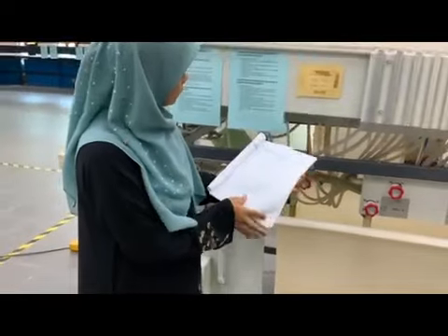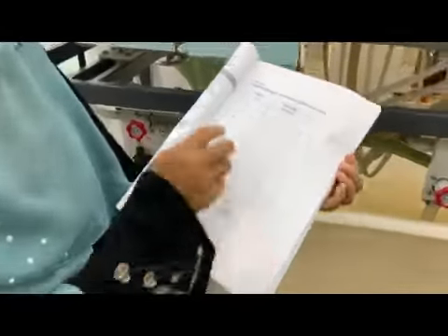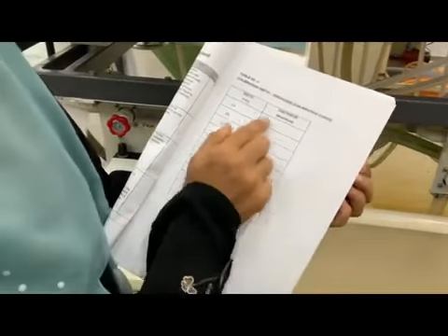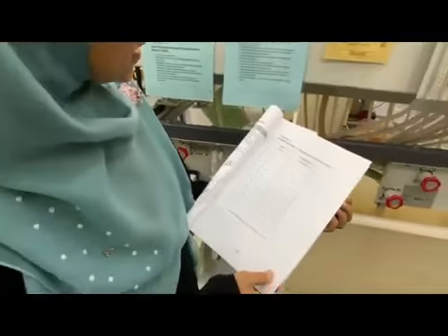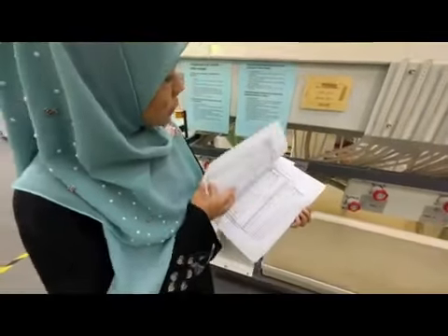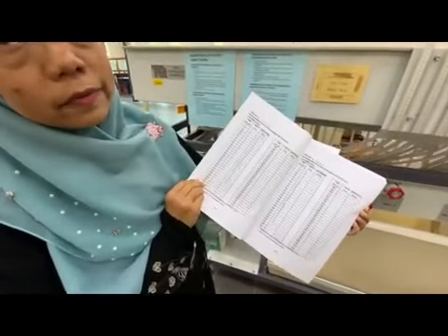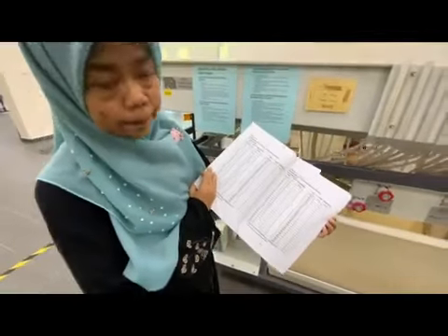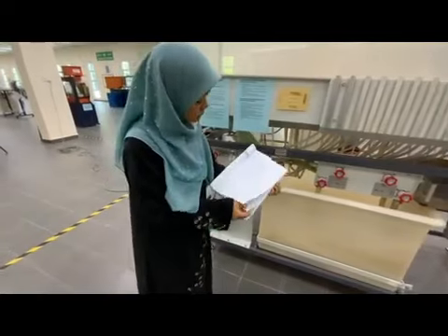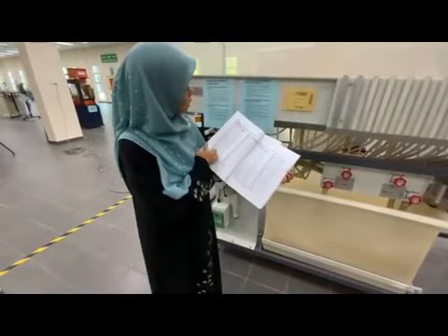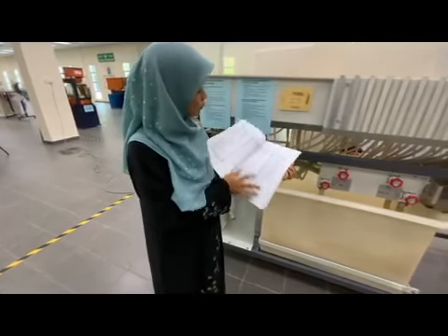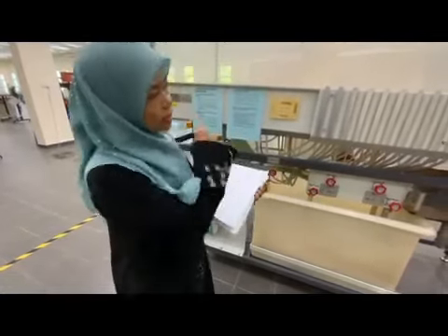In this experiment, you will have three tables. The first one is Table 1, the calibration of depth and discharge. You will get the data and plot the data to get the calibration curve. The second one, you will run for the first experiment, what we call the determination of the storm hydrograph for the upstream. Then the second experiment, you will do the determination of the storm hydrograph at the downstream, and the final one we will do for the multiple storm for the entire catchment area.